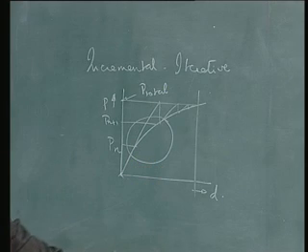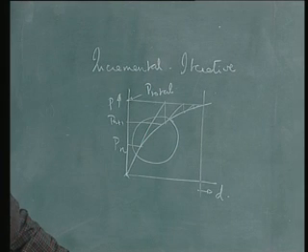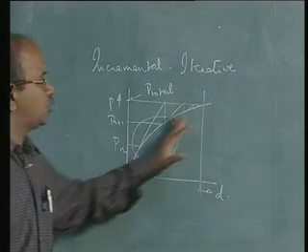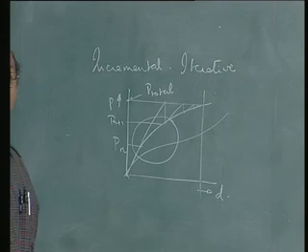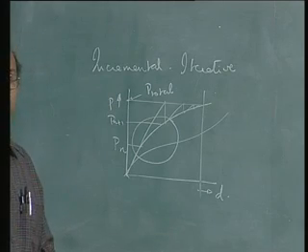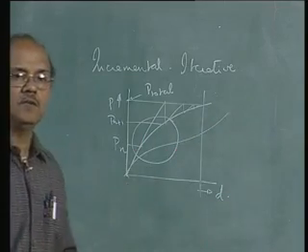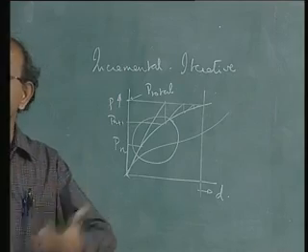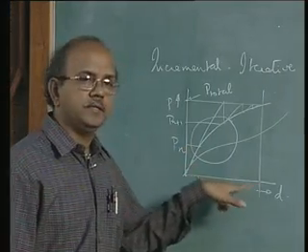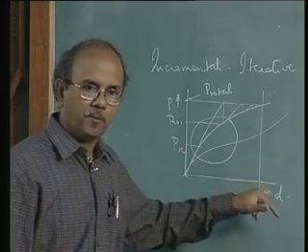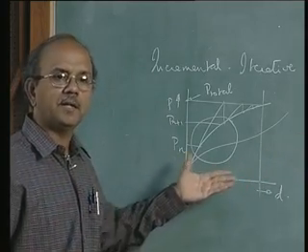This may converge, but maybe it may take more steps than that, but there is a good chance. But sometimes, if the curve is not so nice, say something like that, then you will not get convergence. You will not get convergence. Okay, you have to necessarily follow this curve by an incremental force approach. Is that clear? So, in other words, to answer your question, you can put the whole load here, and the procedure is the same. If you get convergence, you are lucky. If you don't get convergence, you have to come back and cut the steps and so on.